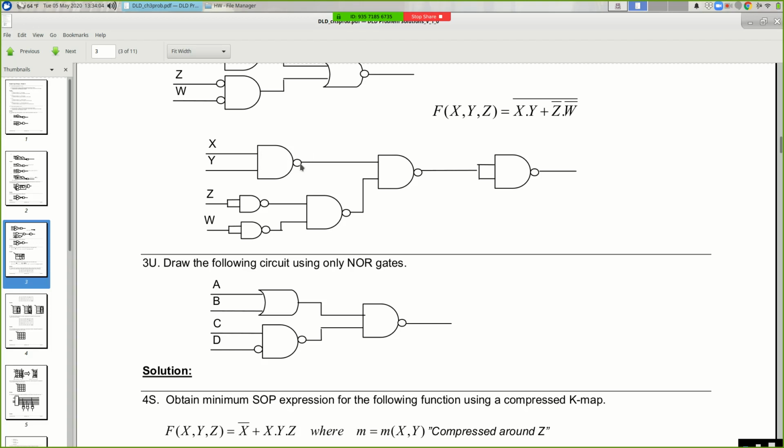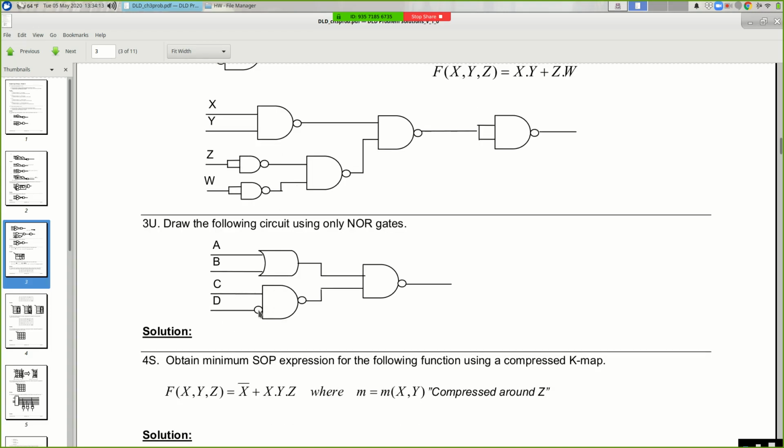This is really an AND gate with the output going through an inverter, but the little bubble here says take the AND gate's output, flip it. Well, we can flip inputs too. So this says take D, put it through an inverter, and put that inverted input into this gate. So we just draw a bubble there, and it means just flip D.